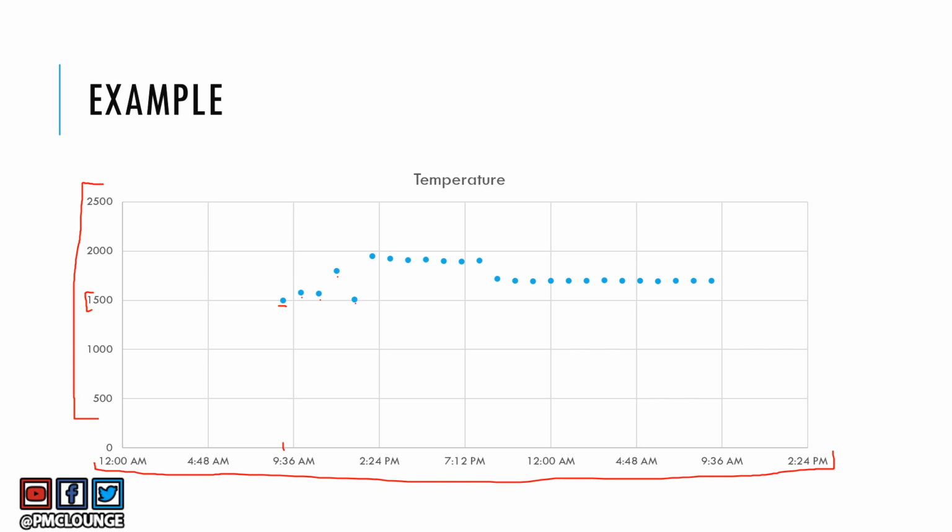Now, certain things that you need to know here. Number one is upper control limit, which is also known as UCL. You already know that at 1700 degrees Celsius, sand is going to turn into glass. So the upper control limit that you are considering here is around 1800 degrees Celsius, because you don't want to unnecessarily burn the furnace and take the temperature above 1800 degrees Celsius, because that is of no use.